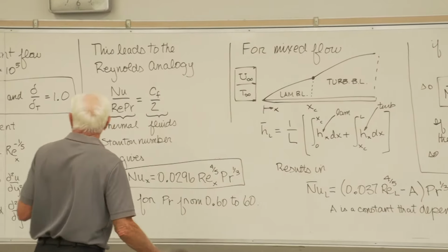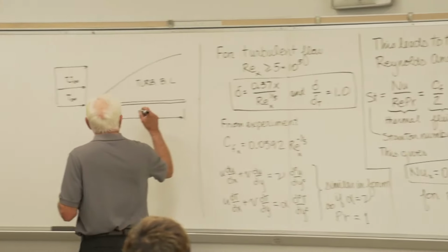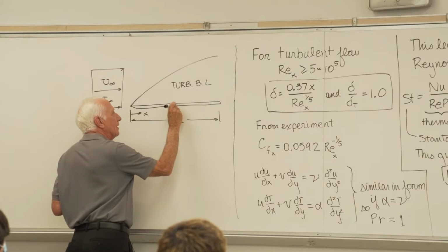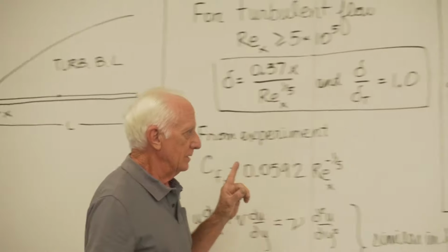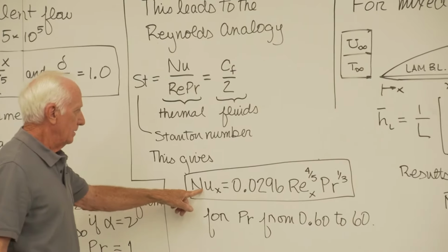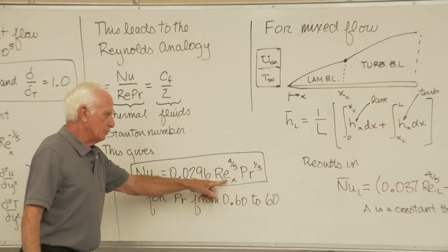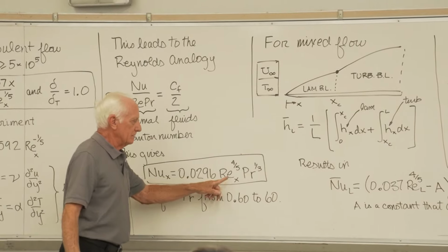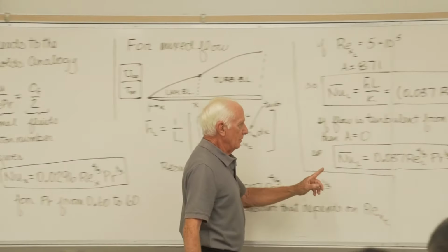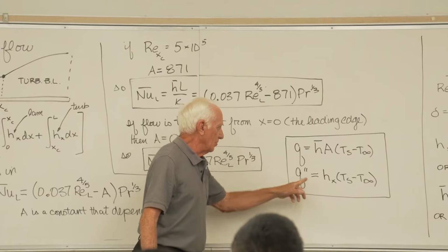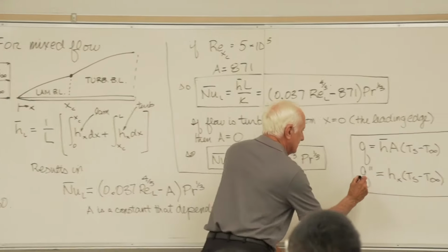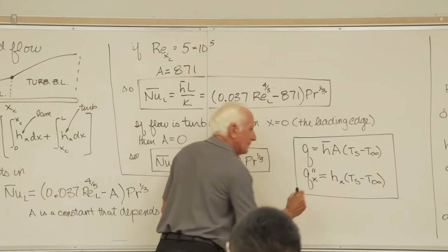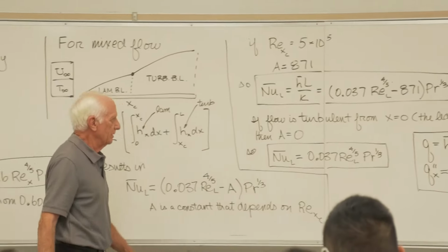Again, turbulent flow. Someone says, I want to find the local heat flux at X equal L over 2. Local, subscript X, right here. What do you put in for X? L over 2, got it. What do you do then? Put it in here and get the local heat flux. Sometimes you can put an X here. That just indicates at that particular X location.